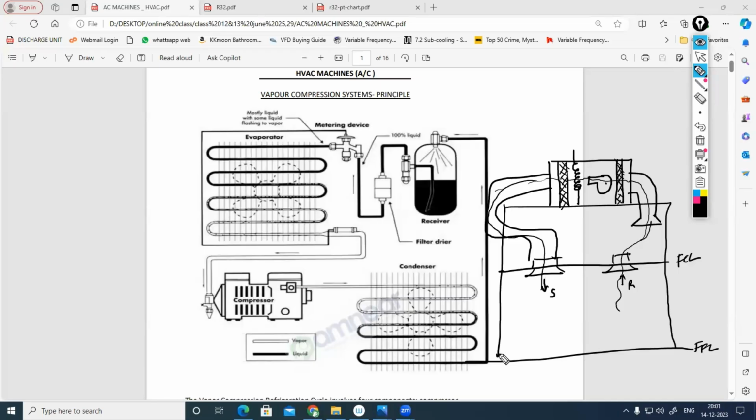So what all things do we need? First, an air conditioning unit, meaning your cooling coil or heating coil. Then you'll have a circulation fan, because it is not possible to circulate the air otherwise, right? You need air terminals. These are air terminals only, on the false ceiling. Then this is your duct. We have the supply air duct, and this is your return air duct.